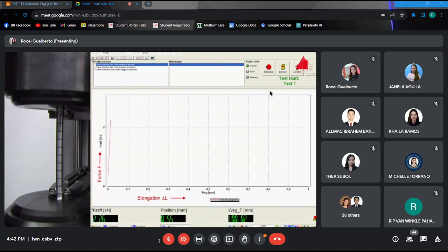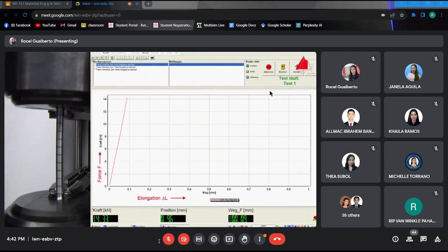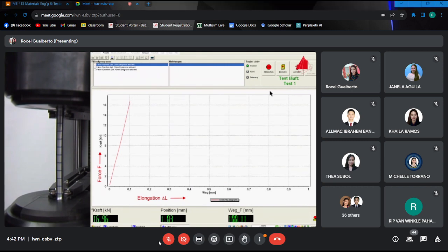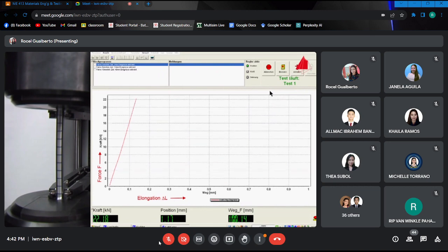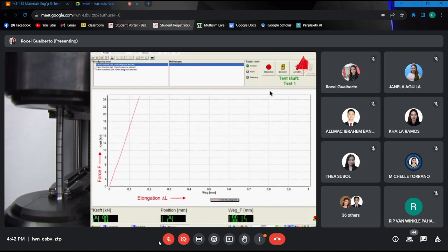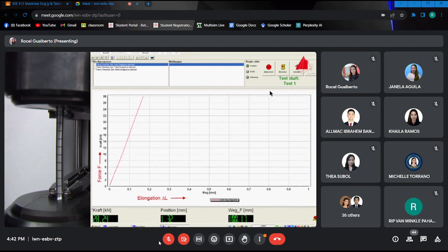Force and elongation are proportional and form a steep, straight line in the diagram. In this area, the material behaves elastically. If the test piece were to be unloaded from this area, it would spring back completely to its original length. In materials with yield point phenomenon, the end of the elastic area can be seen clearly.